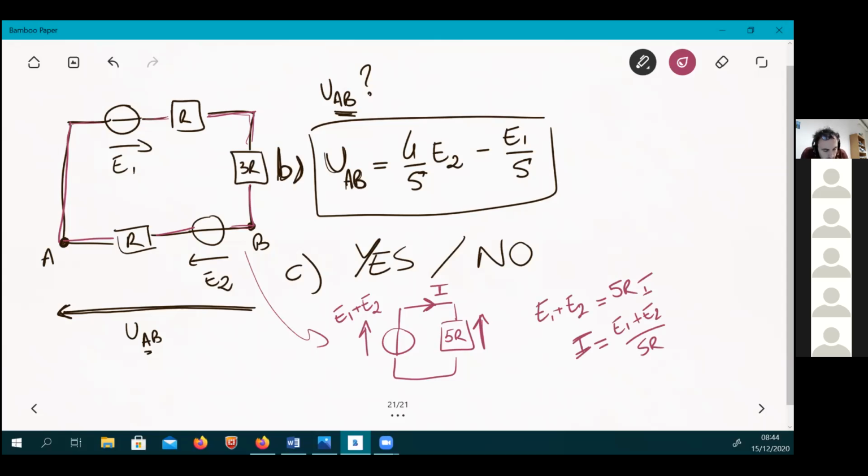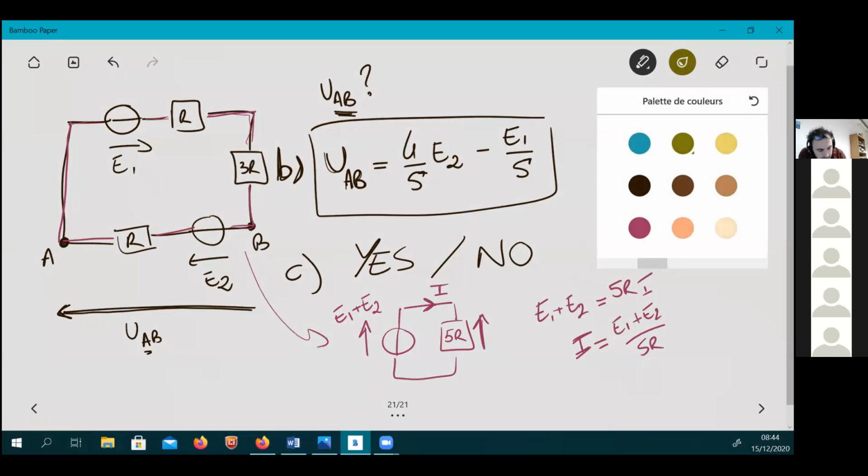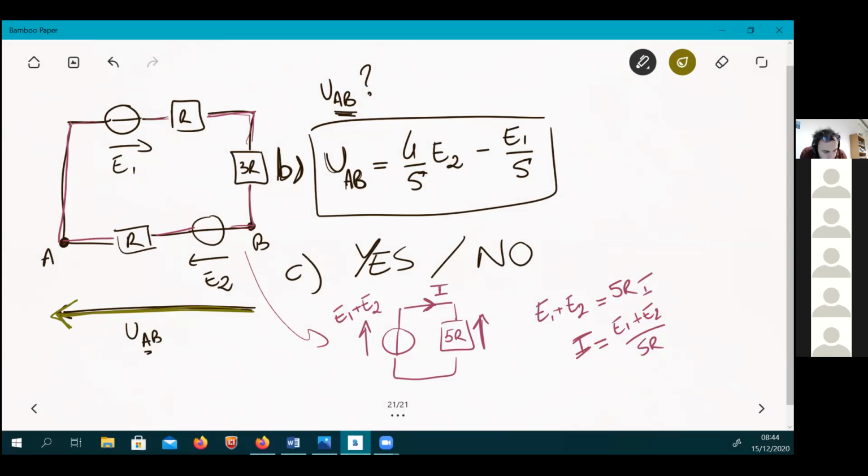So then the question is, what about the voltages here? In between these 2 points, it's already fixed that you have a resistor and another voltage generator. If you start simplifying your circuit, like what I did here, then you have changed everything, because now maybe A and B is here, you see? So now the voltage you consider between A and B is 0, which is not correct.